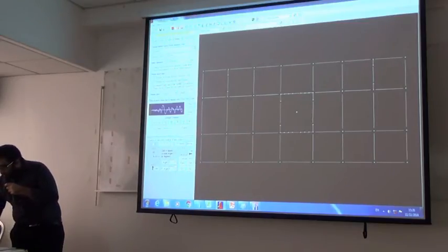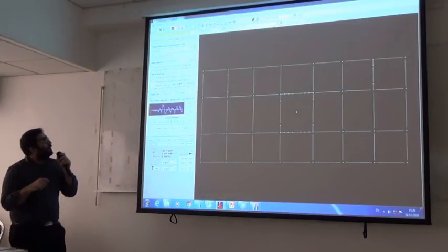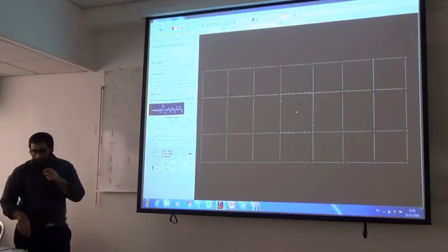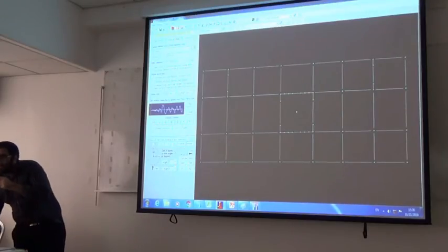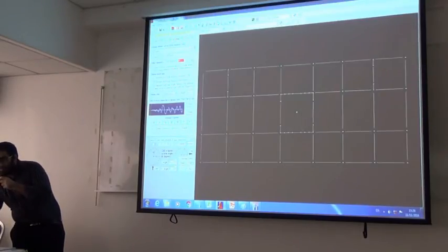And also, if we want to see the histories of the forces, we need to select the option to show us the time histories of the forces. If you select the first option shown in here, this will be only envelope forces, right? And if I want to select the column, I will just drag over the column like this, and all of the columns below are already selected, right? So just plot it.